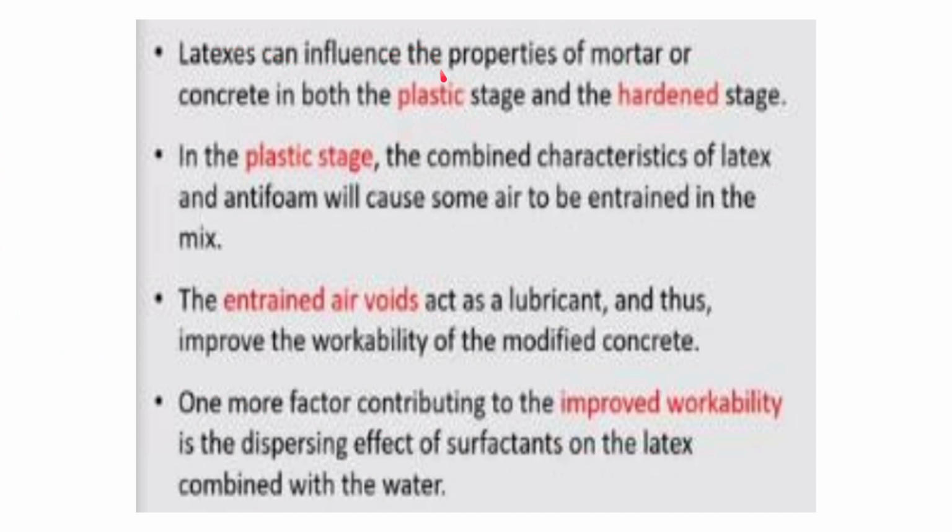Latex can influence the properties of mortar or concrete in both the plastic stage as well as the hardened stage. In the plastic stage, the combined characteristics of latex and antifoam will cause some air to be entrained in the mix. The entrained air voids act as a lubricant and thus improve the workability of the modified concrete.